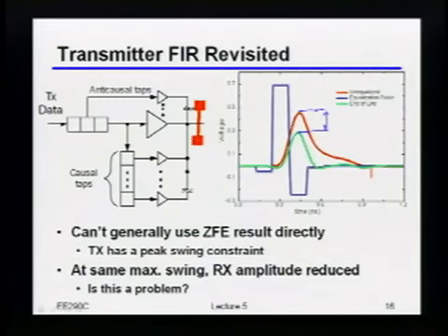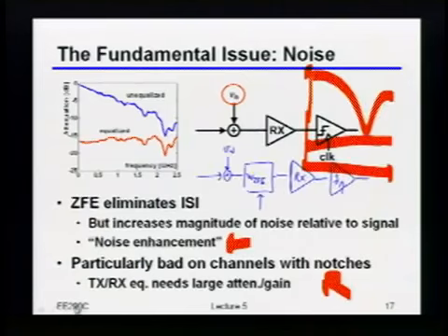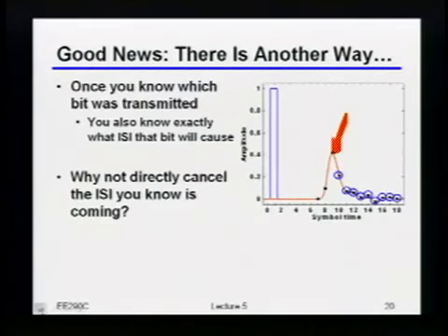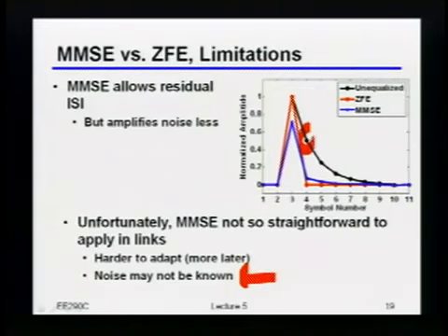Okay, so there's actually optimizations that people tend to do in the other way, which is they may do something like use the DFE to cancel only that one tap afterwards, and then let the linear equalizer take care of everything else after it. Okay, and the advantage of doing that is that now your linear equalizer is dealing with lower bandwidth signals. So that's a great question.